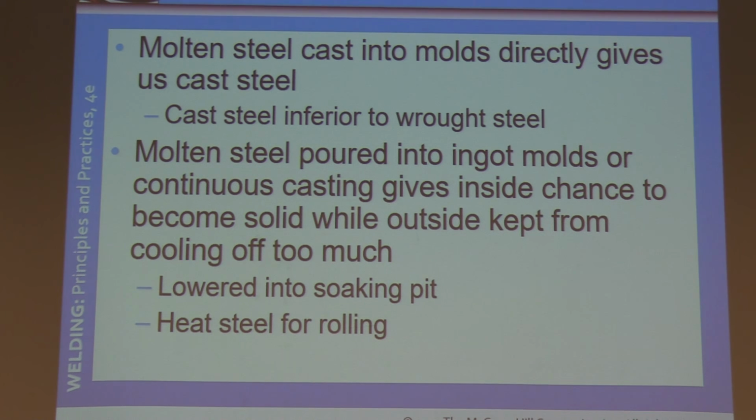I'm going to read down page 66 under deoxidization. In most steelmaking processes, the primary reaction involved is the combination of carbon and oxygen to form a gas. Proper control of the amount of gas evolved during solidification determines the type of steel. If no gas is evolved, the steel is termed killed because it lies quietly in the molds. Increasing degrees of gas evolution result in killed, semi-killed, capped, and rimmed steel. Go down to the second paragraph from the bottom on that right-hand column, called capped steels.